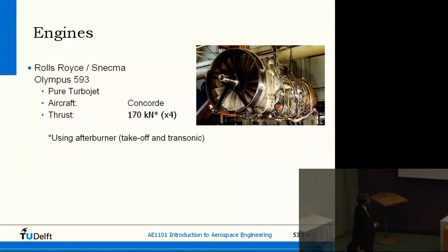8.5 is another one, and the Concorde is even different, and this is a pure turbojet. Of course it's an older aircraft and you have higher speeds there. Remember that for a high-speed aircraft, you still want your VJ to be higher than V0. So there, the low exhaust speed is not good news. So for higher speed aircraft, and that's also why the military fighters are not flying with turbofans. Okay, I leave it at this.